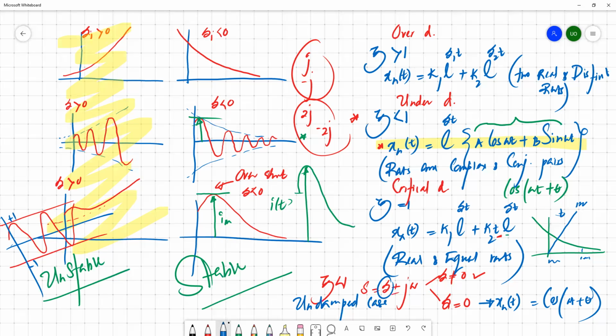So where you see sigma is 0, in that undamped case, you have kind of an oscillating response. Basically, the amplitude is between +1 and -1. So we have four types of systems: overdamped, underdamped, critically damped, and undamped scenarios.